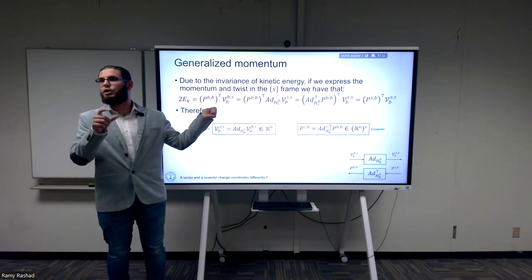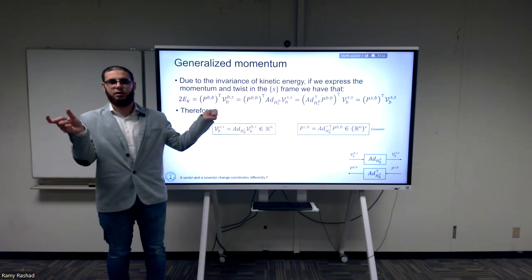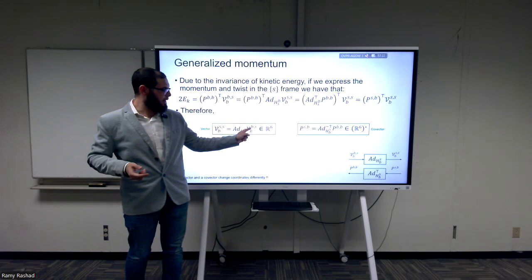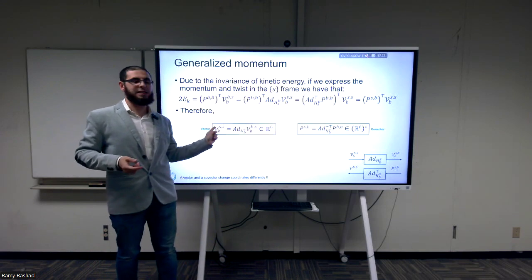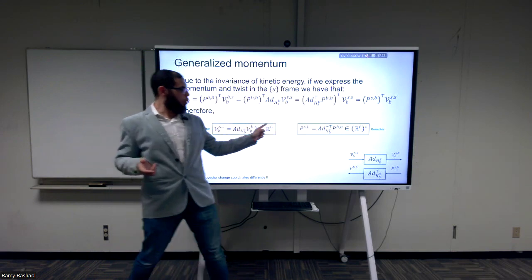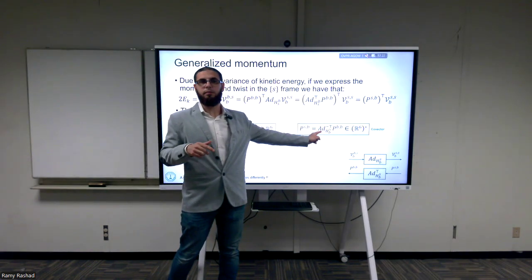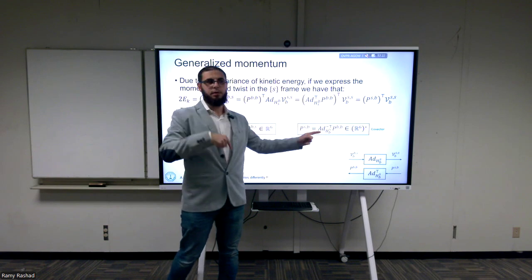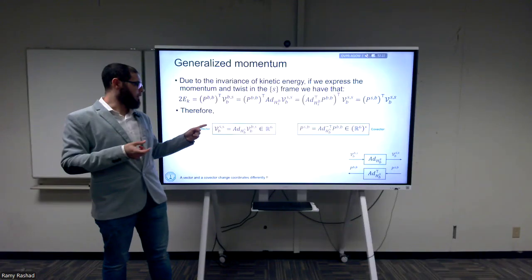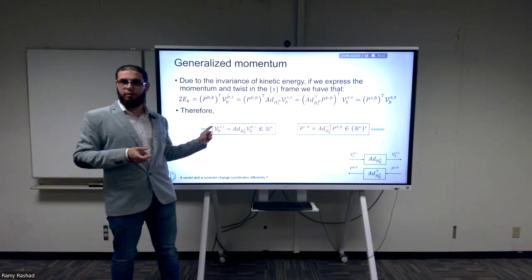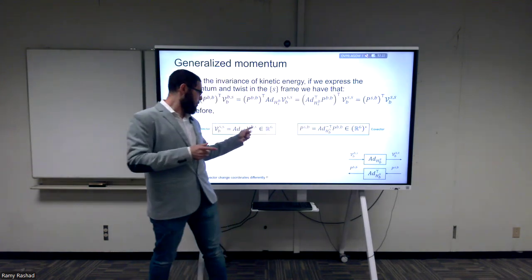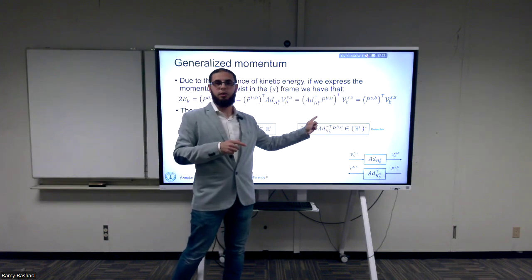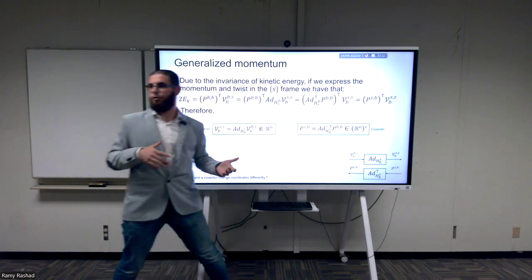When I change coordinates from frame B to frame S with a linear velocity, I multiply it by a rotation matrix. So to go from a linear velocity in the B frame to the S frame, I multiply by R. When I go with the momentum, I go by R inverse transpose, which is R. When we do the same with the torques, I transform the twist by R, and I transform the torques or the angular momentum by R transpose inverse, which is the same R.